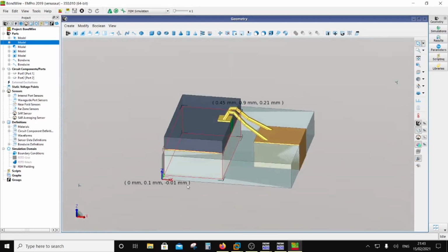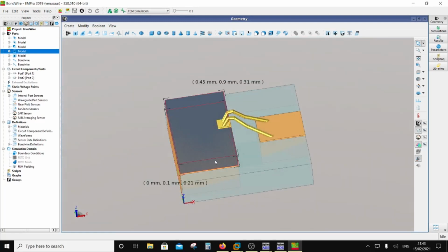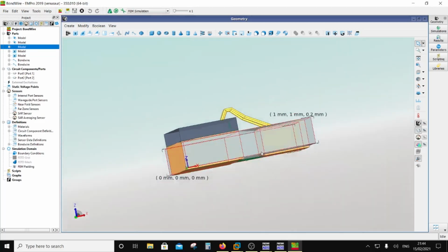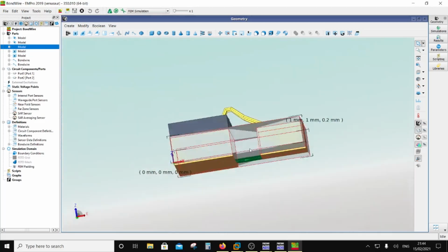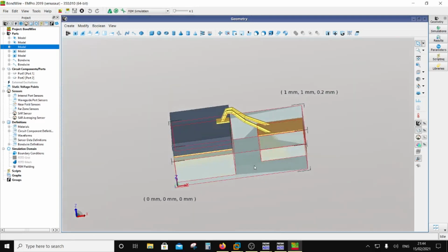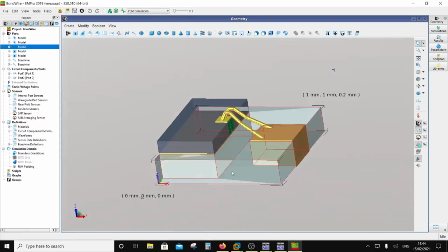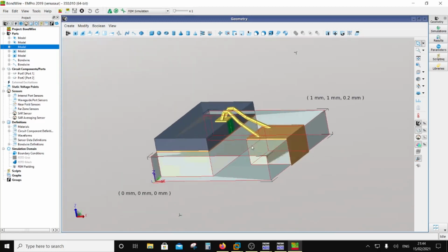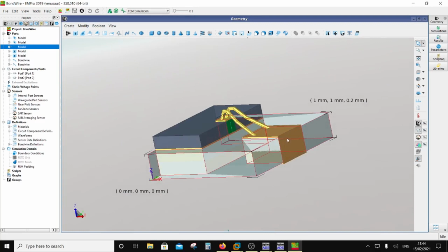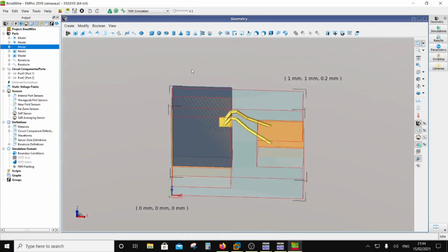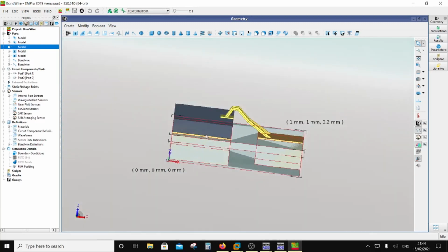This is one solid piece of ground, and on that there is gallium arsenide sitting, and this is your alumina, Al2O3, right? This is usually used in most of the processes to do the QFN. This is usually done by an HTCC process. So that's alumina sitting there, and this terminal is the pin. Usually you will see that this is like a QFN, but this is a small piece of that QFN.